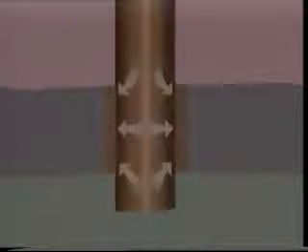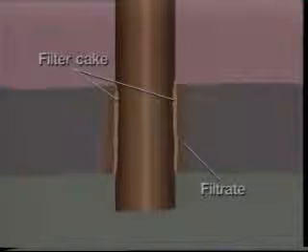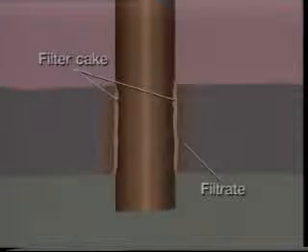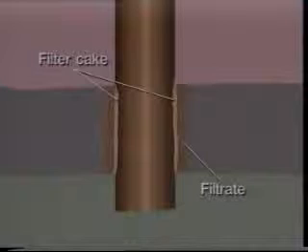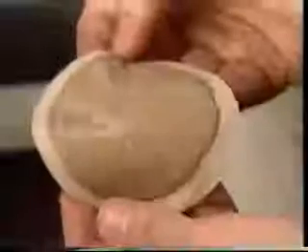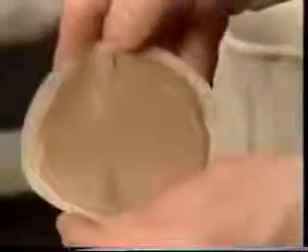The third major category of the mud properties is that of filtration behavior. The loss of liquid from a drilling fluid is controlled by the filter cake formed from the solid particles in the mud as they screen out on the drilled formation face. The liquid which passes through is termed filtrate. It is water in water-based muds and oil in oil-based muds. The term filtrate loss or fluid loss refers to this loss of liquid from the mud. In a well-designed mud system, a thin, tough filter cake will form, stabilizing the wellbore and protecting the formation.